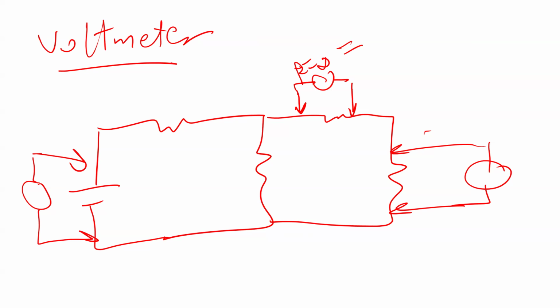In other words, we have a current here, and I'm going to call it I. What I have to measure is actually I times R. This is R, the resistance here. So the voltage drop I have to measure is actually I times R, assuming all the current flows this way. In reality, because you added a new resistance, not all the current is going to flow this way; there is some current flowing this way. I'm going to call it, for example, IV, the voltmeter current.